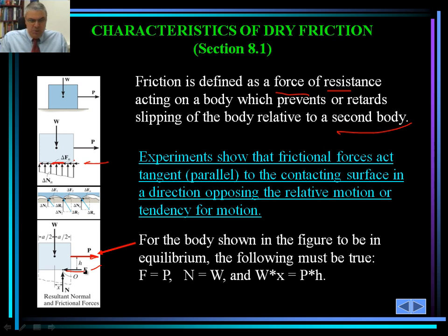Remember that every time you're trying to pull or move such a block, there are also inertial forces as well. But those are applied in dynamic situations, because inertial forces don't come into play unless we apply the force P very quickly. But for the sake of friction, P is usually applied slowly, and there will be no variation of P over time, although there are some, but again, for static calculations, we don't consider those.